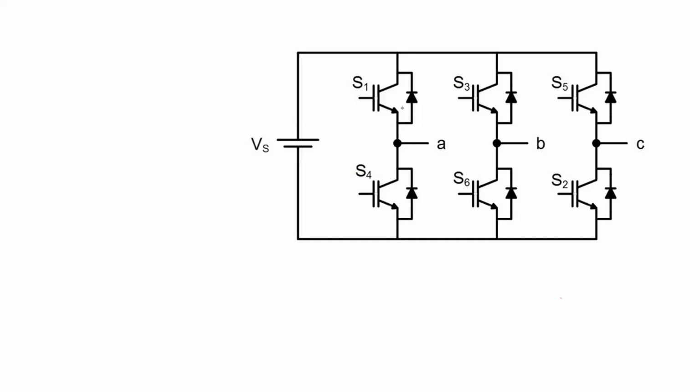In today's class, we will discuss the deadband circuits for inverters and the effect of dead time on the output voltage waveform, and also we'll see how to compensate that voltage loss in case of dead time circuits. So, deadband circuits. First thing is, why exactly do we need these dead time circuits?